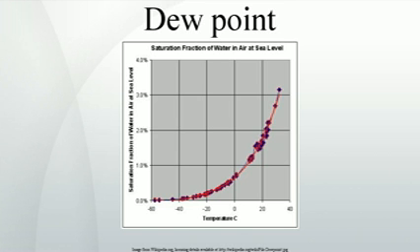The dew point is a water-to-air saturation temperature. The dew point is associated with relative humidity. A high relative humidity indicates that the dew point is closer to the current air temperature. Relative humidity of 100% indicates the dew point is equal to the current temperature and that the air is maximally saturated with water. When the moisture content remains constant and temperature increases, relative humidity decreases.